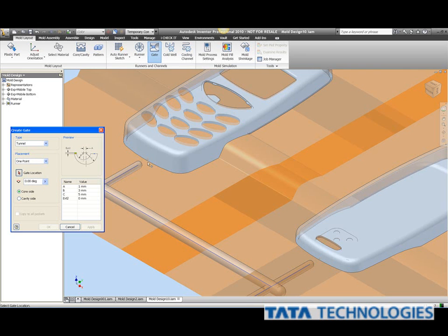I'm going to go ahead and rotate this 270 degrees, and we can see it making the transition back to the runner system. So I'm going to simply go ahead and apply this, and we can apply that right into the design. We also have an option when we have more pockets and things like that to copy to all pockets at once. But in some cases, we enjoy a little bit more control inside of our design, and I can simply add that in.